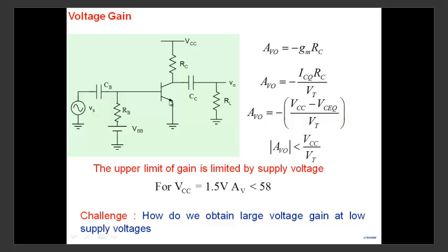Power output, but we also said, remember, that my collector current is more sensitive to base emitter voltage and less sensitive to collector emitter voltage, transconductance. In that view, when I talked about transconductance and all that, beta was nowhere in the picture. All of you are thinking of beta because you are applying the signal from the base here. I can apply the signal from the emitter. Emitter can be my input, and collector can be my output.